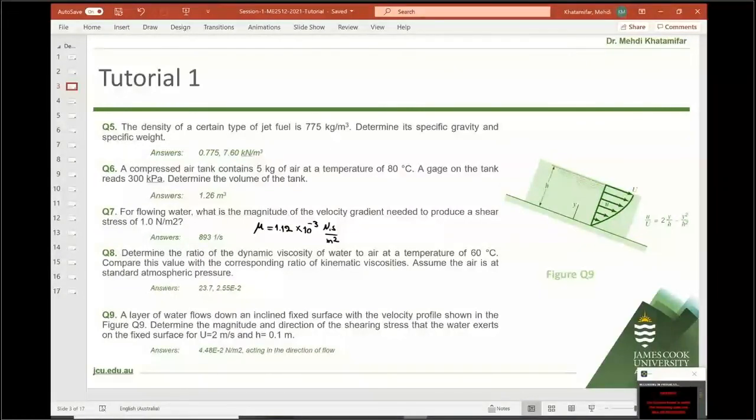Did you write your note for the ideal gas? Always write the absolute value. At the end of the semester, when you're coming back, for this session you have 2-3 important points which I may use for the final exam questions. One of them is that. So make sure you know those important points. Write it in red. Another important point was about the slope of that line for the viscosity. The slope is the viscosity. Instead of giving you the viscosity, I may draw a line and push you to find the slope and then get that. Write it in red.